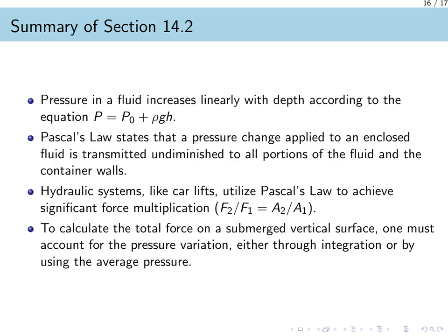A direct consequence of this is Pascal's law, which states that a change in pressure applied to an enclosed fluid is transmitted undiminished to every point throughout the fluid. We then explored a powerful application of this principle, the hydraulic lift. By applying a small force to a small area, we can generate a much larger force on a larger area, with the force multiplication equal to the ratio of the areas.